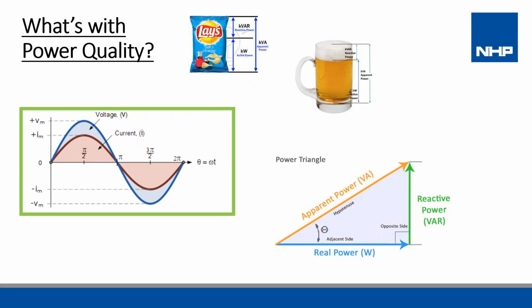So inductive loads and capacitive loads will absorb energy during part of the AC cycle, which is then stored in the device's magnetic or electric field. This energy then returns to the source during the rest of the cycle. Capacitors are set to supply reactive energy. Inductors are set to consume reactive energy.